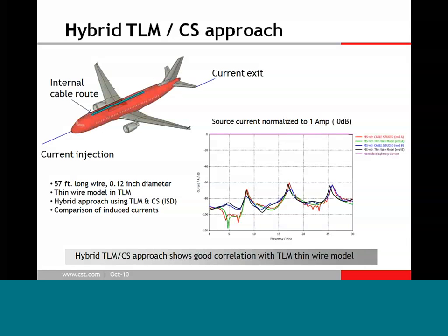In order to validate this approach, we did a simple case where we had a thin wire, a 57-foot long wire inside the aircraft, and we modeled it directly using the thin wire in the 3D solver, and then we also modeled it using the hybrid approach with Cable Studio and compared the results.